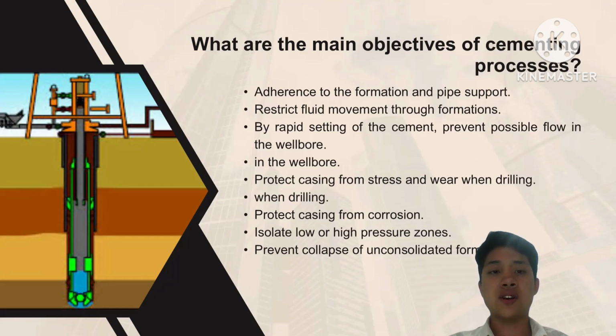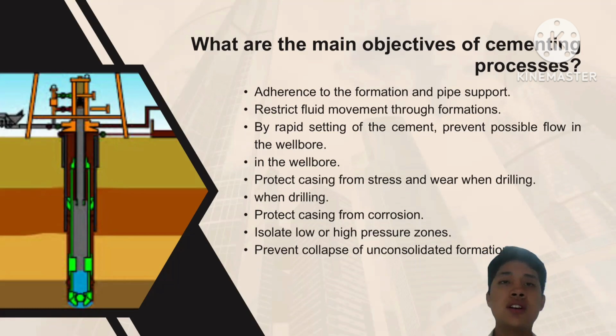Additionally, the rapid setting of cement helps avoid unwanted flow inside the wellbore, ensuring a safer and more controlled environment. It also protects the casing from damage caused by stress, wear, and corrosion during drilling operations.